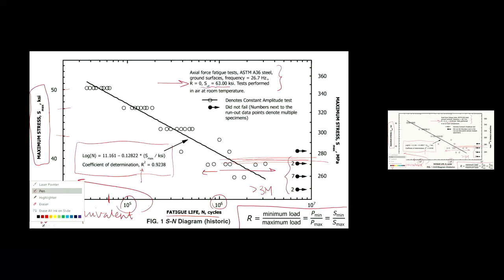So low cycle fatigue is the part of the plot that we've done a lot of hand waving on. It's this part of the plot up here, right? Where we're at low cycle fatigue, so less than 10 to the 3, 10 to the 4 cycles. And we just say that if you stay in the high cycle fatigue range, then you have stable crack propagation, you have an endurance limit, right? These things we're very comfortable with. Don't go there. But some applications require